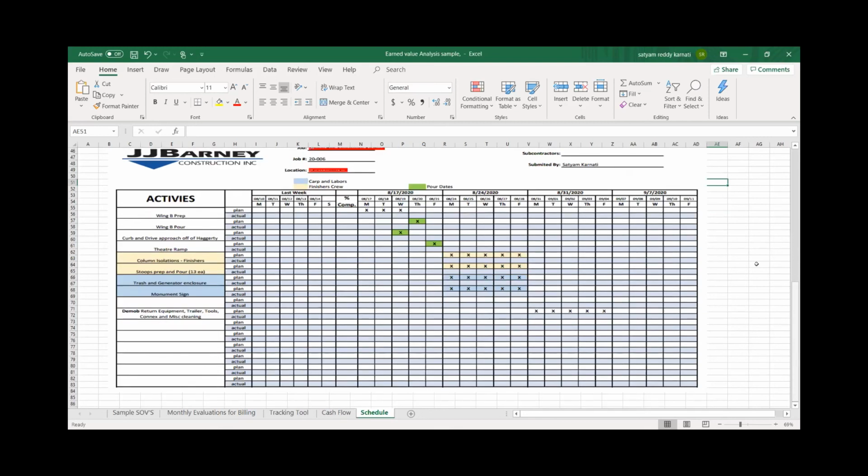It also helps us with safe work practices, because we have enough time if we have any activity that needs special safety attention, or quality, or prep, or submittals and RFIs. So the foreman actually gets a chance: okay, this is what I'm doing in the next 2 weeks. Let me take a look at these details and ask questions.